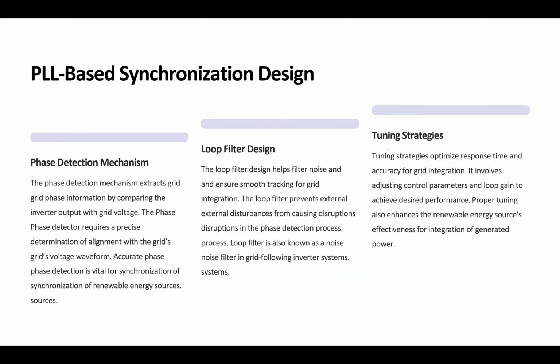We already talked about that. This is the phase lock loop synchronization design. For designing PLL-based synchronization, you need to have a phase detection mechanism. There are tons of different phase detection mechanisms that extract the frequency and phase in the terminal. The very simple one is the zero crossing.